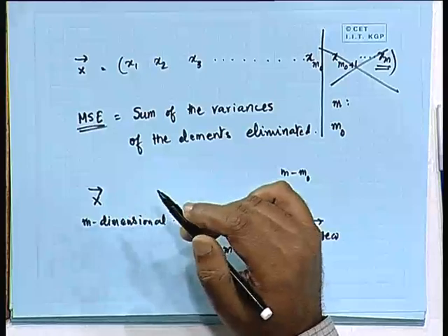One of the things which all of you must have done is the use of orthogonal transforms, which serve as the basis functions, and we can reconstruct a signal on the basis of using those orthogonal functions. We know about the Fourier transform, we know about the cosine transforms and their discrete versions in the form of discrete Fourier transform, discrete cosine transform, etc. All these things are giving us this T matrix in some form.